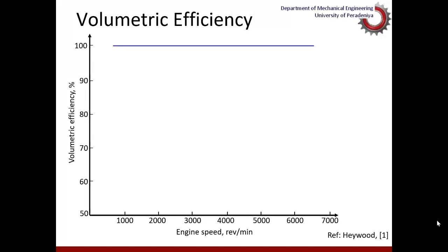With this background, if you look at the volumetric efficiency under these different flow situations, ideally we would like to have a volumetric efficiency of 100%, but we will never be able to achieve this in practical engines. One reason is that initially, due to quasi-static effects, there is a drop of volumetric efficiency.